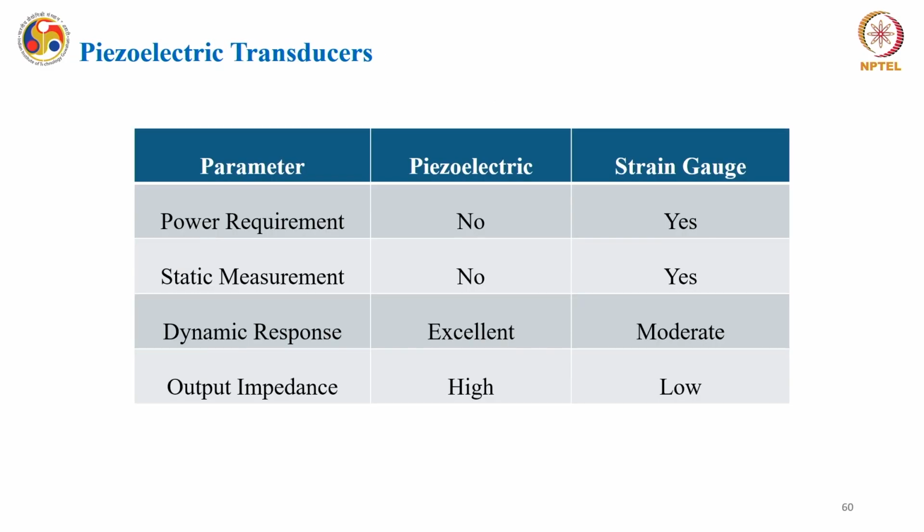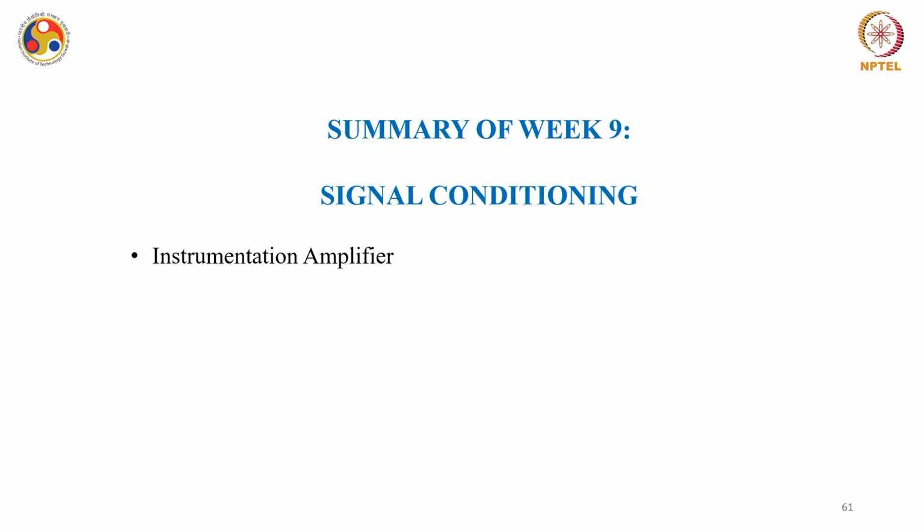Then we compared it with a strain gauge, and we found that from some points of view piezoelectric transducers have excellent properties, particularly the dynamic response of piezoelectric devices was very good, but they were not suitable for static measurements, because in a static measurement the charge that it generates cannot be stored, it vanishes easily. So it has a major advantage in terms of dynamic response, and for static measurement strain gauges were found to be more suitable.